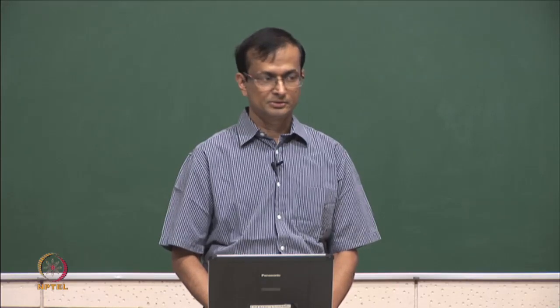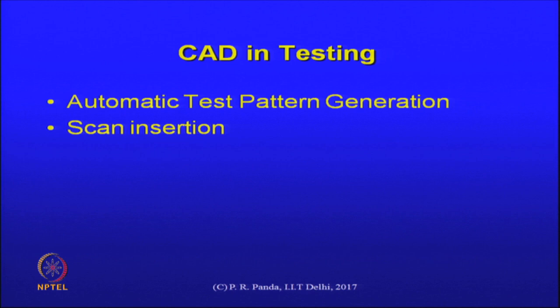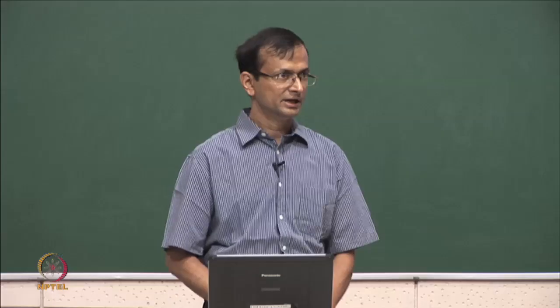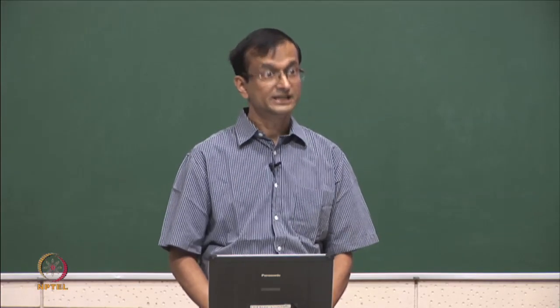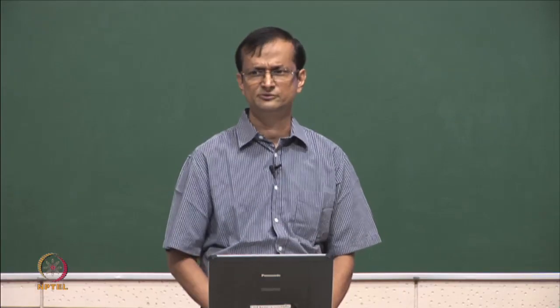Parasitic effects are there in the real chip, but it is not as though they are not there in the model that is being simulated. That depends on what you have modeled. If your model is very simplistic and did not take some of those effects into account, then indeed you do not observe them, but we can do our modeling taking those effects into account. Like when we already have the layout, there is enough information for us to answer many other questions.